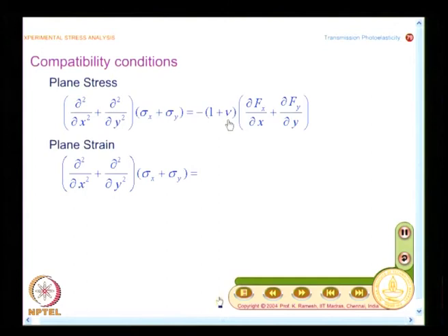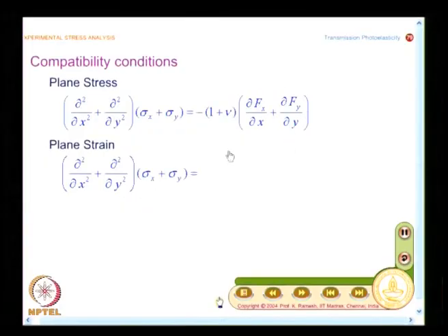Poisson's ratio, which is a material property, whereas the equilibrium condition was not a function of any of the material properties, whereas the compatibility condition is a function of the Poisson ratio. Suppose you eliminate the consideration of body forces from the point of view of simplicity, you find the right hand side becomes completely 0. So, this equation will be independent of elastic constants again,